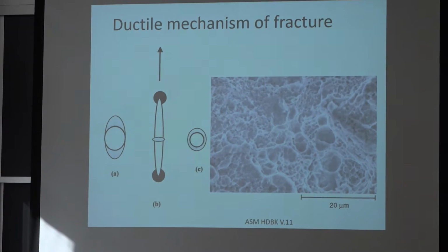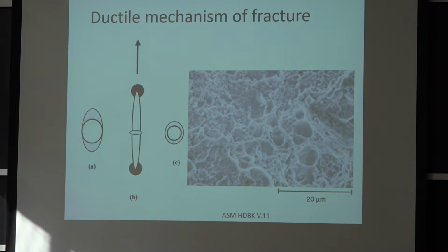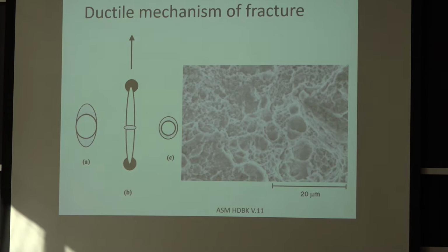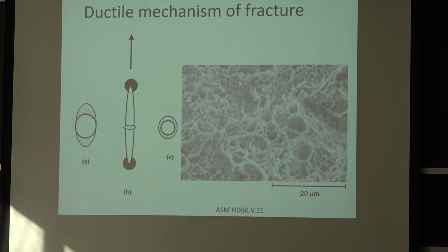This slide, I left it in. It's when we were looking at those fracture surfaces this week, we were talking about whether it happened all at once, whether it didn't happen all at once. And this very specific fracture surface, if you see it on a weld metal or anything that's broken, it means that you really had the overload. These are ductile dimples. You see the little round area. So it's all you can expect out of the material. When it fails this way, it means that it did its job.